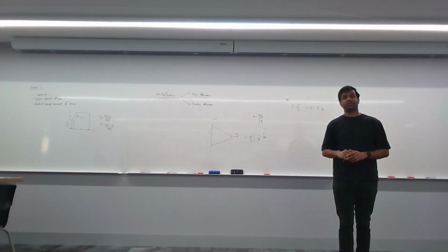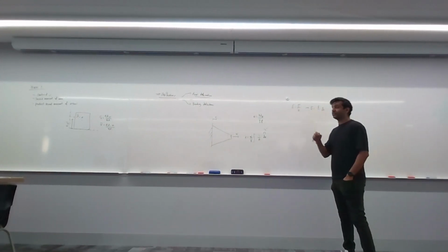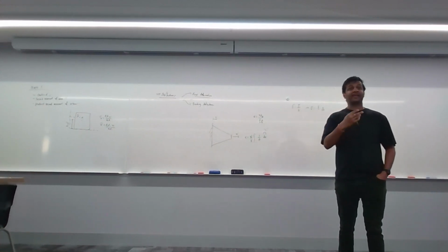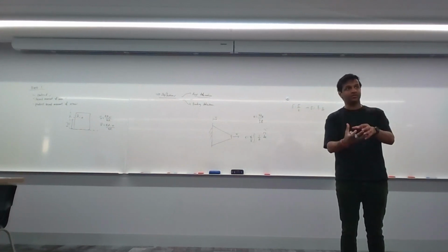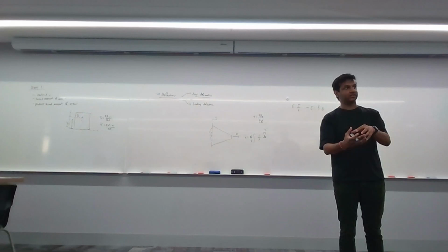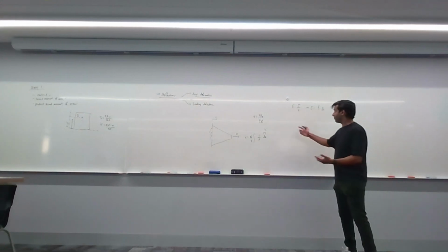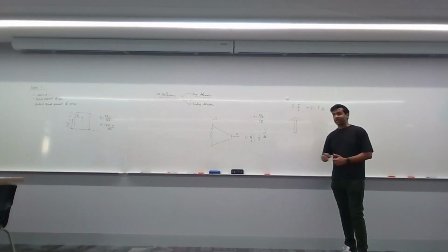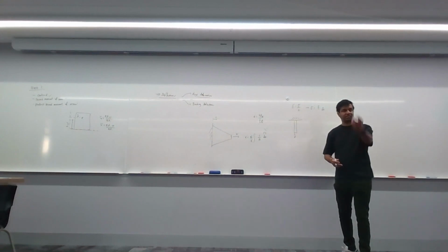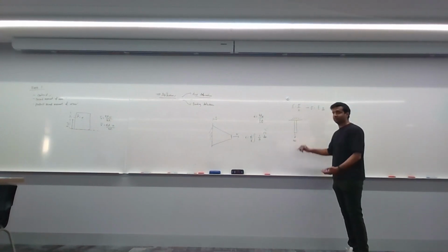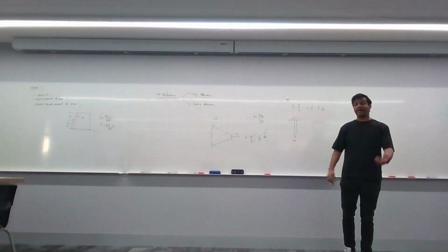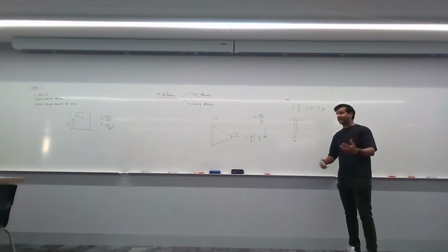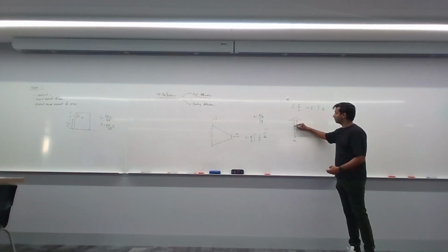The other thing about the integration that you need to keep in mind is if the question ever gave you density or unit weight, what that means is your material has got a weight to it, and you have to include that in your calculations as well. A popular version of that is if you have something that's hanging from a fixed end at the top. If you have a load here that has a certain axial load here, say it's 40 kilonewtons or 50 kilonewtons or whatever, right? But this thing is a heavy rod. You also have to take into account the fact that there's gravity that's also pulling this down.